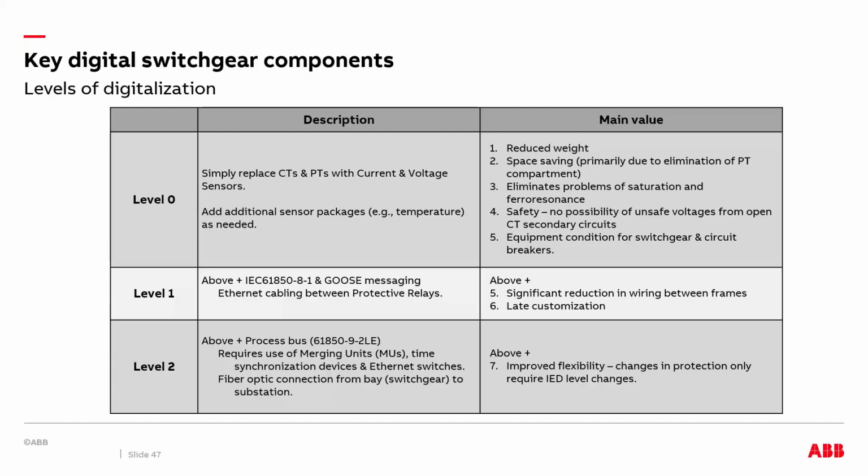Now, the most amazing level 2 is where you include process bus communication, which is IEC 61850-9-2 LE. This includes sampled measured values. It takes the analog inputs from current sensors and voltage sensors and sends them to a merging unit or protection and control relay which has IEC 61850-9-2 LE, and it reads and digitizes them to share with the other relays which have the same protocol.